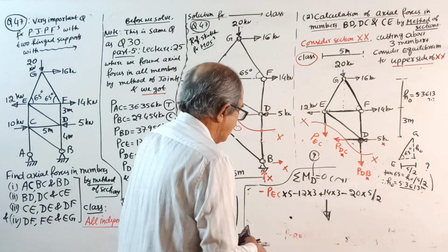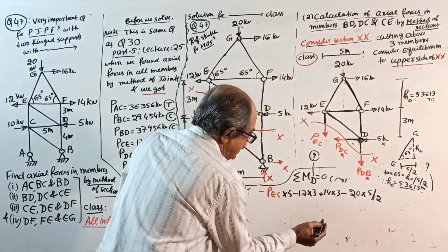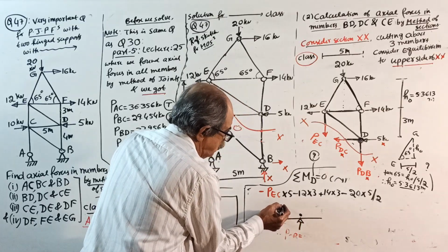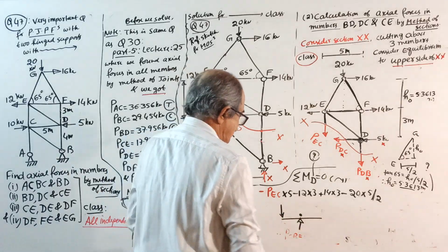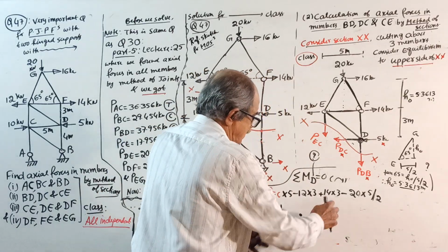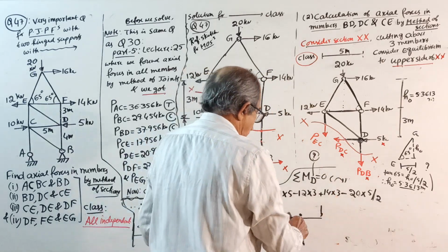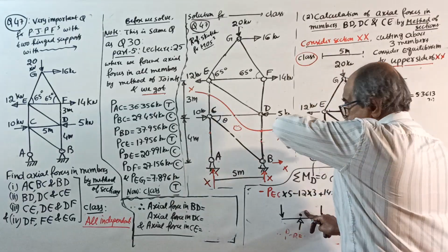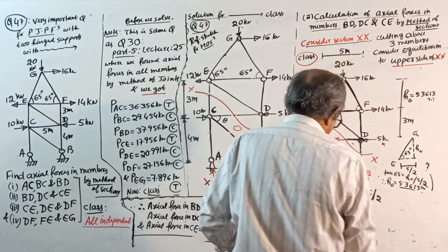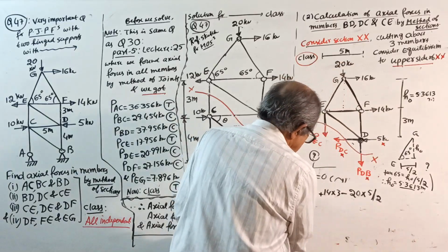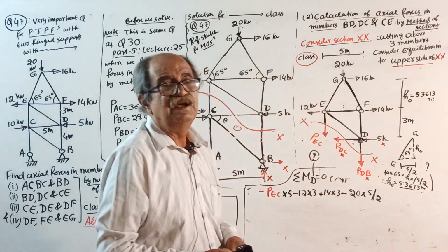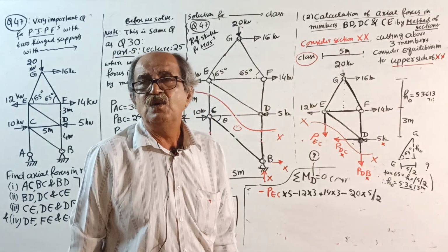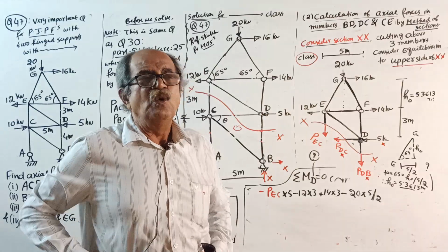See, by chance, if there is a beam and you take moment about the left-hand, overhanging side, and one load is there, then a load here, load into this distance is clockwise. But what about now? This is anti-clockwise. So don't give the wrong idea. When you teach, you learn first. Don't give such a wrong idea. Downward force will always create clockwise moment? No.